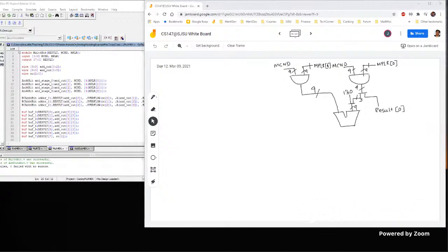Now this adder has two things: one is the 4-bit output, and the other is the carry out and sum, right? From there, we are picking up 1 bit, the LSB, as a result, bit 1, and the rest of the 3 bits joined by the carry out, making 4 bits, go into another adder.